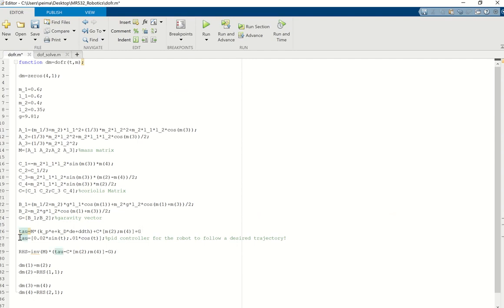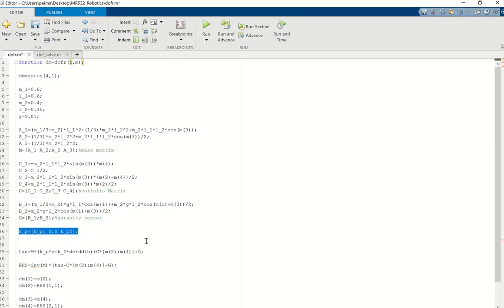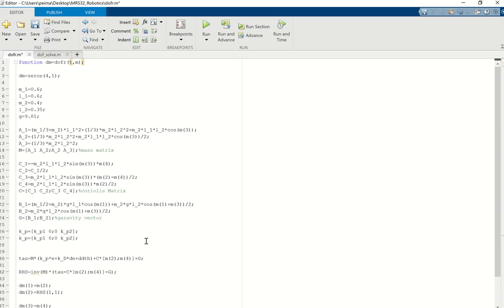So now we are designing modified PID controllers. This is our new theta, but we have to define, let me delete this because it's going to confuse you. Please type this. Kp, but as I said, this is decoupled, so it's diagonal. I'm going to say Kp1, 0, as I said here, and 0, Kp2. So they can be distinct. This is the diagonal proportional gain matrix.